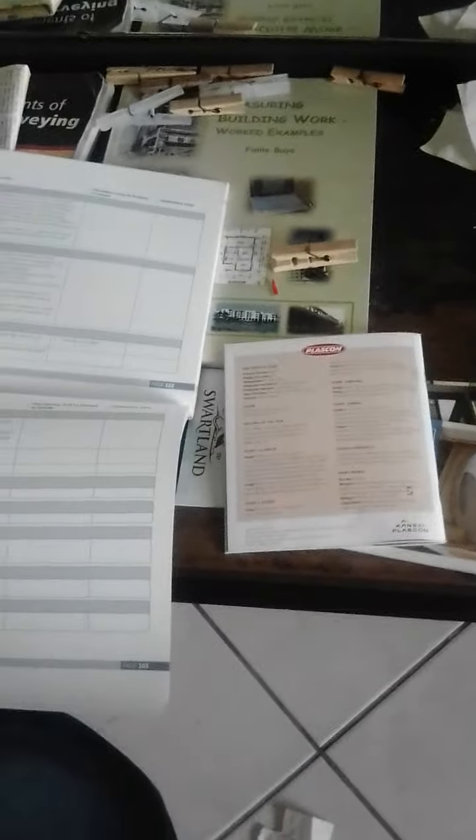Now, the spread rate on the information bar on your tin of paint helps you to calculate how many liters you need, based on how much a liter covers. So for example, let's say you've got 100 square meters of walling that you need to paint, and you know that your Micatex covers, let's say, 7 square meters.